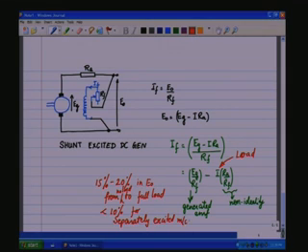This is because in the case of separately excited machine, the excitation voltage is constant and therefore, I F is constant independent of the load, and therefore, that is not going to cause further fluctuation in E g, whereas here there is a bootstrap effect, change in the load, I is going to affect I F, which is going to affect E g, which is going to affect E naught, and therefore, I F. This will cause a much poorer regulation.